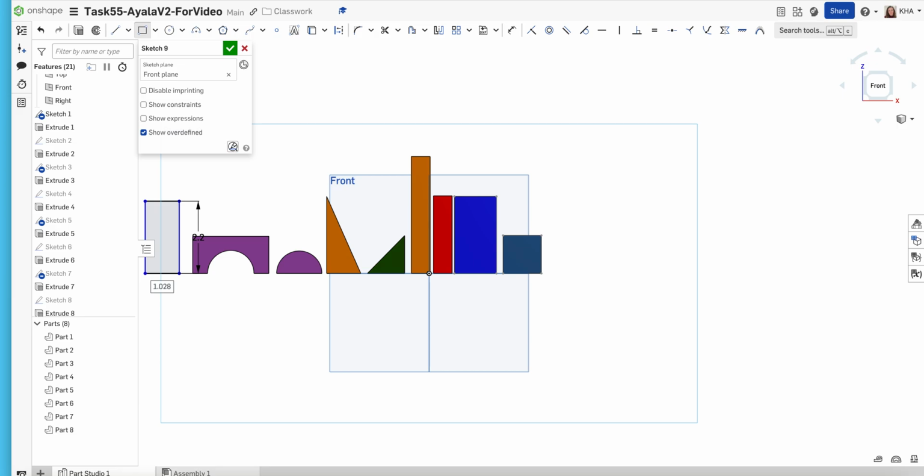So I'm going to put in my own measurement here. Okay. We basically just measured out the diameter of our cylinder and the height of our cylinder. But in order to use the revolve tool, I actually need only half of this rectangle.